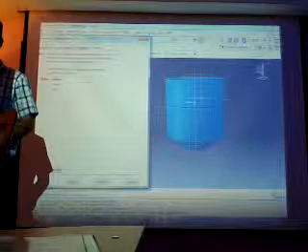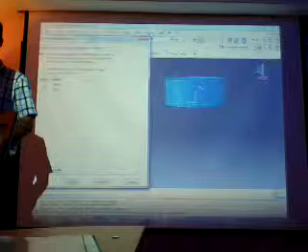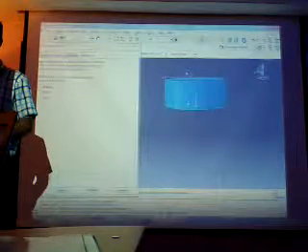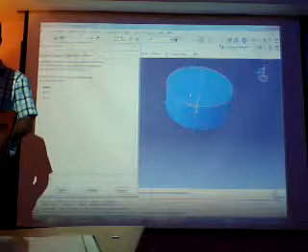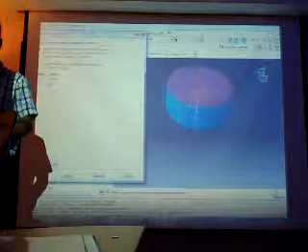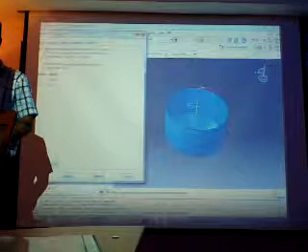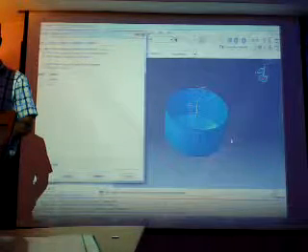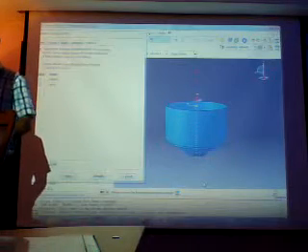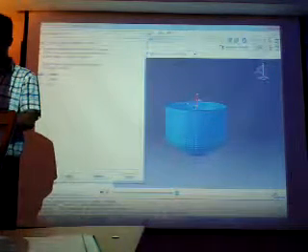Now I'm going to unhide the die. Apply. I have just my billet. In constraint, face to face, I take the first surface, unhide my billet and hide my billet and unhide my die, apply, and take display. Okay, as you can see, the vector is reversed, so we need to take a minus.